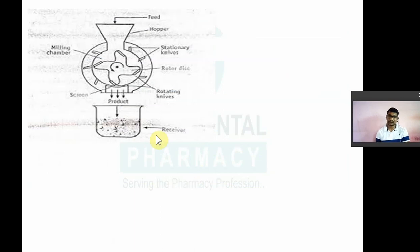This one is a diagrammatic representation of the cutter mill. So here you have stationary knives and rotating knives. This is the stationary knives, and the rotating knives are here. And the gap between stationary and rotating knives will determine the size and shape of your product. Again, a screen is fitted here, a 10 mesh screen. So that will also decide the size and shape of the product. So the gap between these two and the screen mounted over here will decide the product size.